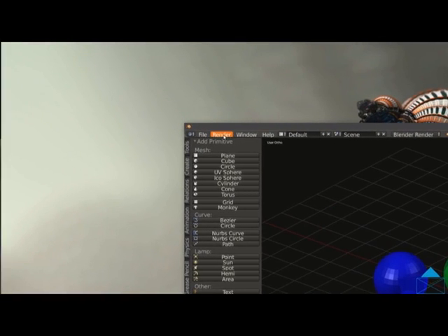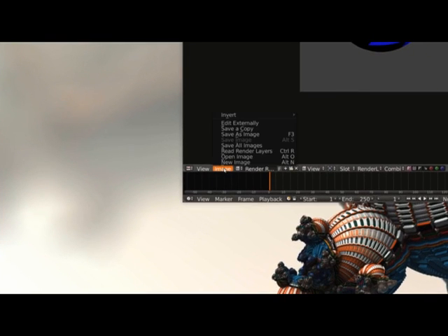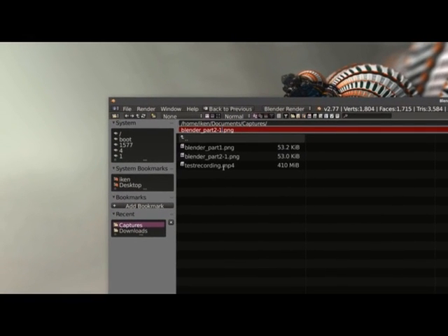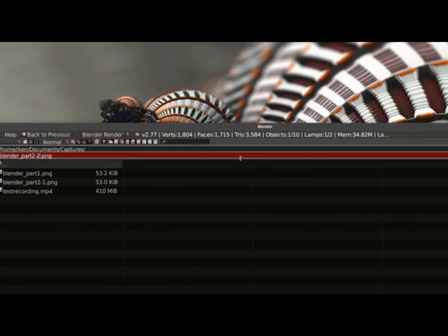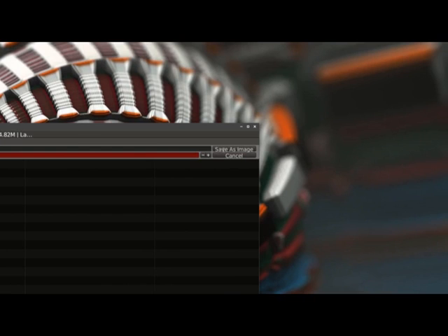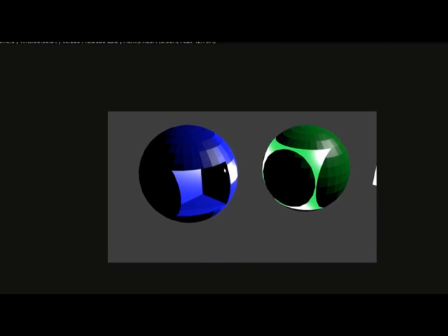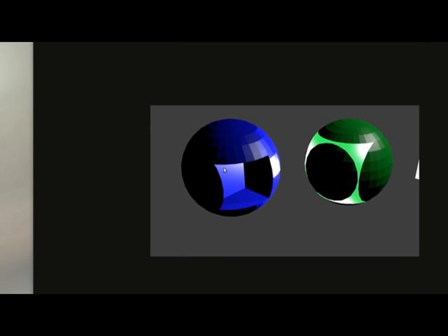Alright, so render, image, scroll down to the image menu, image, save as image, and up here we'll then call this part 2-2. Have to go all the way over here to the other side and click twice to get to the save as image, and now we have another image file that we can simply upload. So that will be our third image of the overall Blender project.